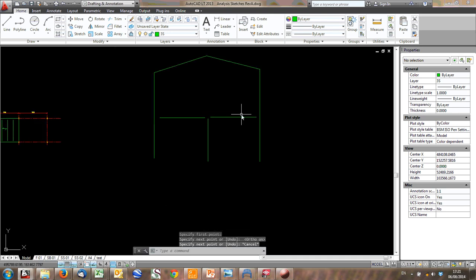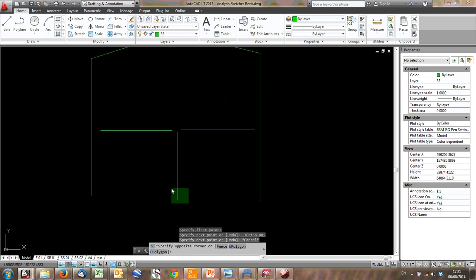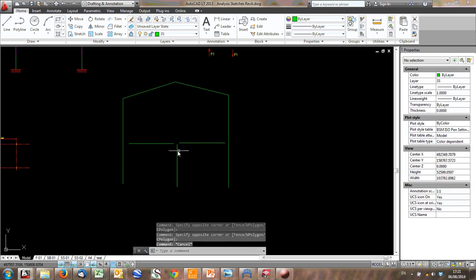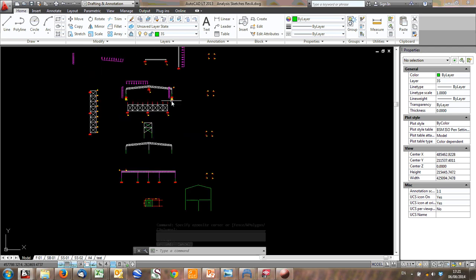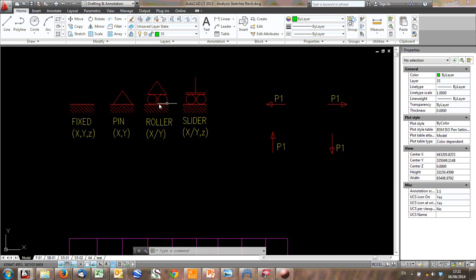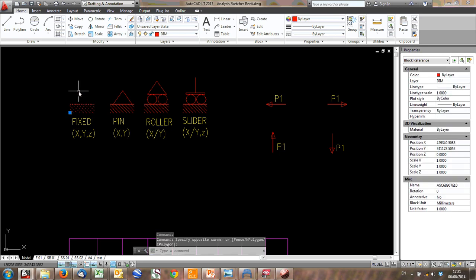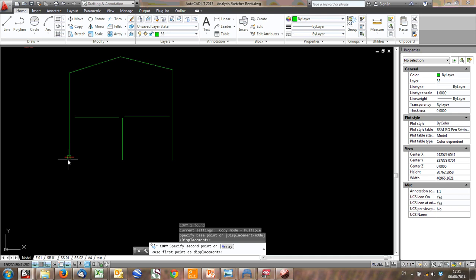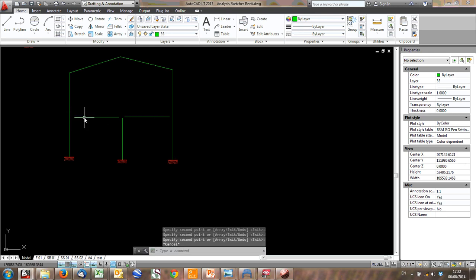If you analyze this, what do the supports look like? Where do you find support from? Well, obviously, you've got some fixed connections or pin connections, depending on what your fixity looks like here. So let's say we're fixed. Let's say we are able to carry the moment here. So we've got fixed support, fixed support. But one thing also, remember, this is a concrete deck once it's cast, so this becomes very stiff.